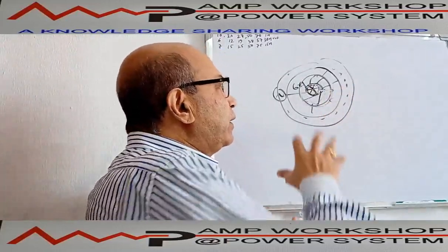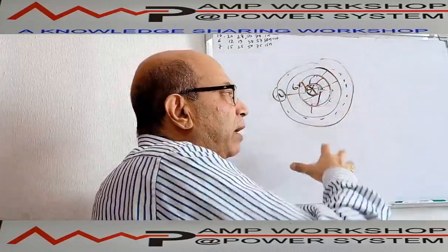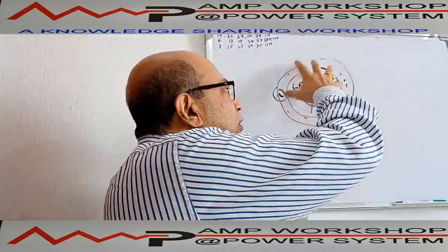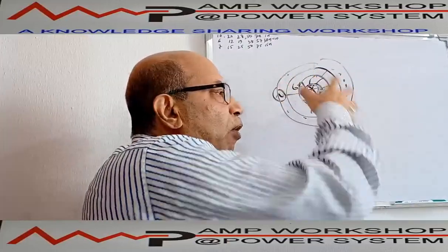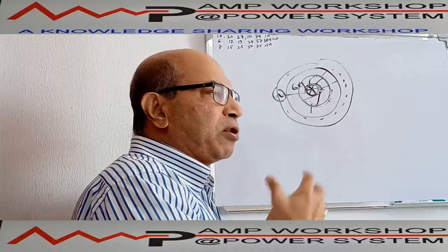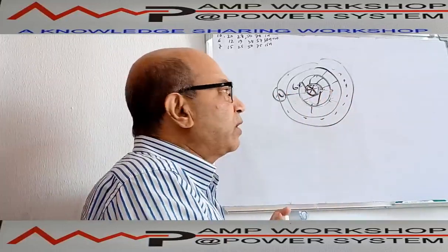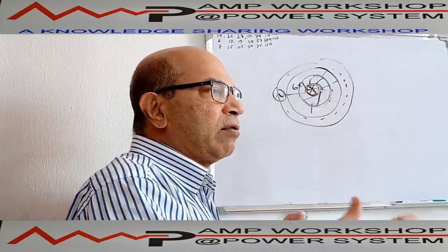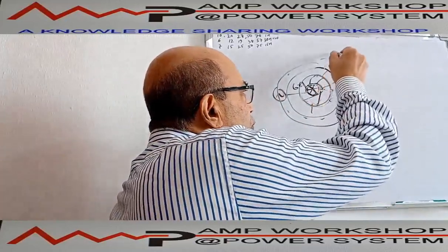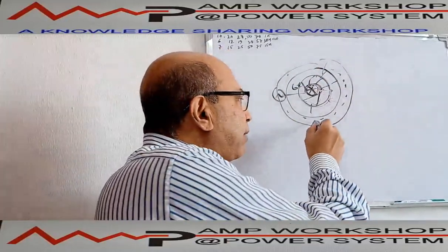Then the fourth point is the entire system. This armor sometimes may come in contact with voltage due to an earth fault or something, and also this total system may be in a polluted area, suppose there are fumes or a plant where petrochemical products are there, sometimes there will be some sulfur dioxide gas. Suppose it is an underground cable, underground there are a lot of gases, all those gases can penetrate through this, and that can damage this armor also. There is a possibility, because the armor is a metal.